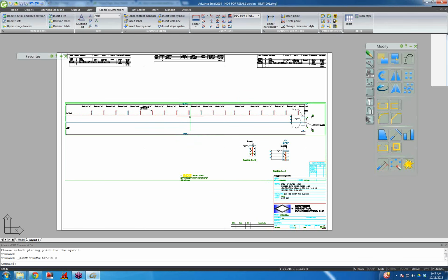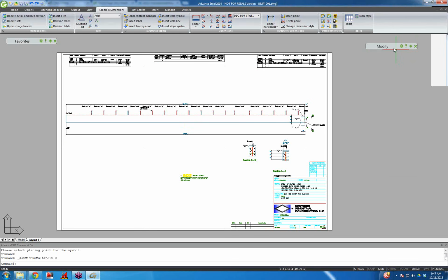The reason they didn't come up in that section BB, you were saying they weren't generated the same. Well, for the section views, the software for this piece uses drawing styles. The drawing style for the main view is not the same as the drawing style for the sections. So that's why the sections are not showing the studs.